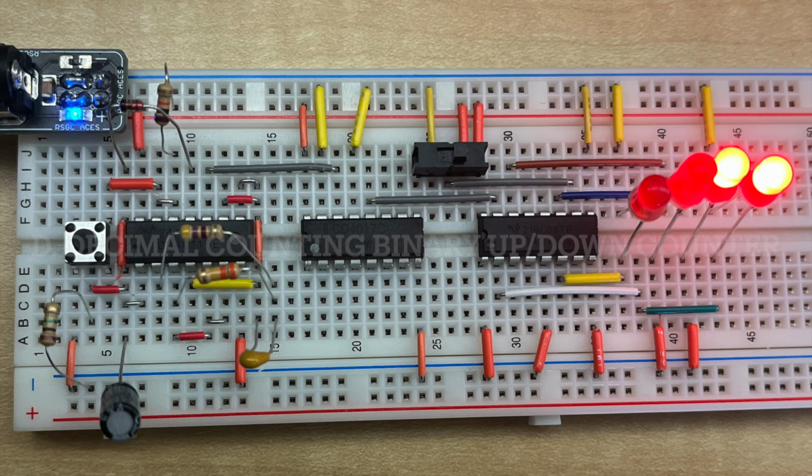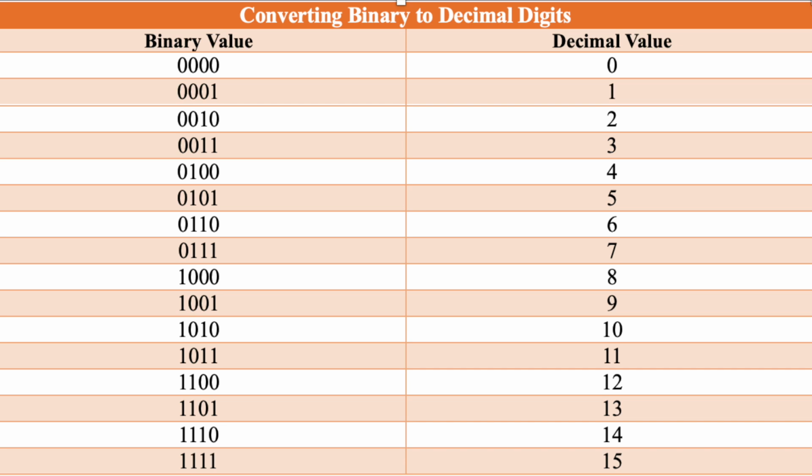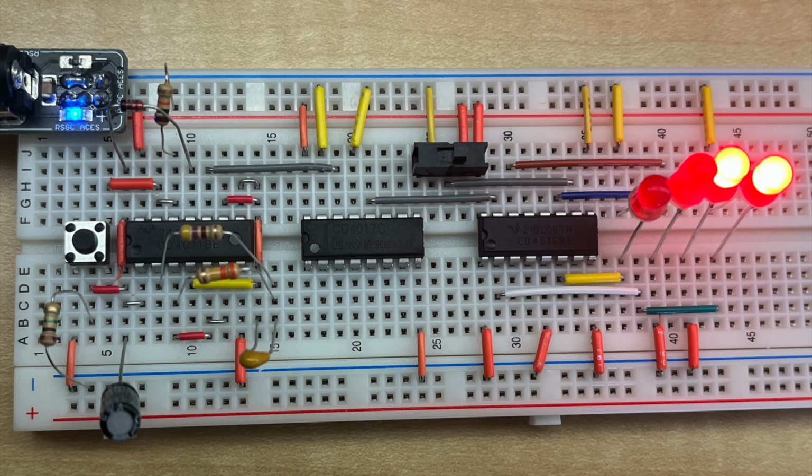The decimal binary up/down counter counts in binary from 0 to 15, or in binary 0000 to 1111. The 4510 IC takes the 1/10 oscillation output from the decade counter and uses internal logic to output signals to 4 LEDs in a determined order to make it appear as binary. It does this by giving oscillation to each of the 4 LEDs, which gets slower for each LED.